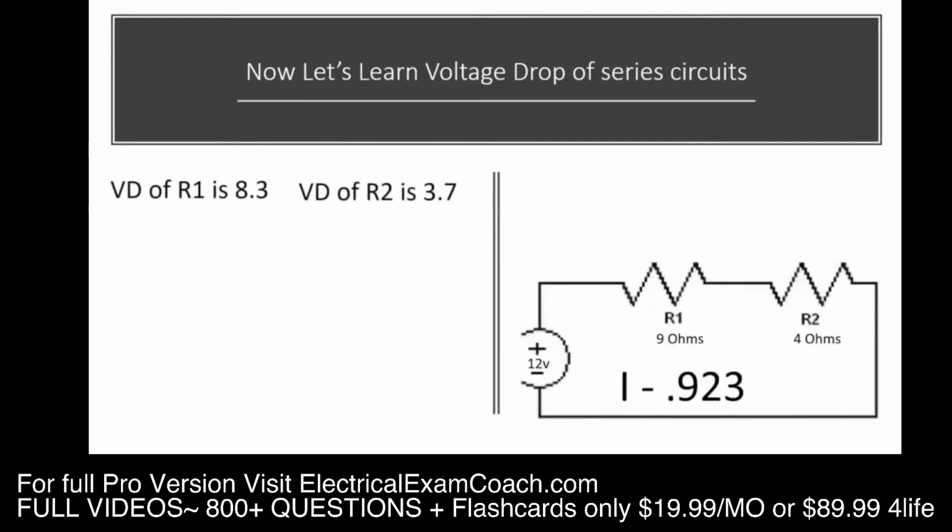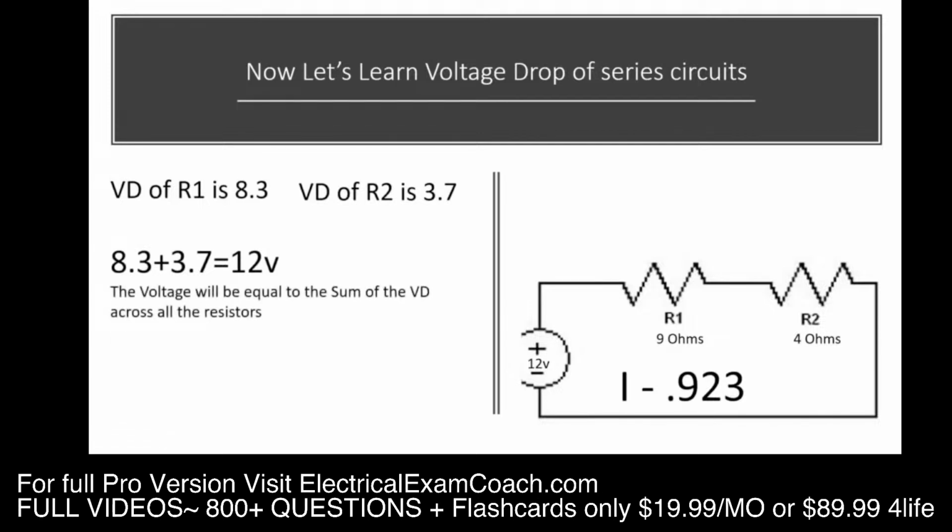Okay, a quick recap. The voltage drop of R1 is 8.3. The voltage drop of R2 is 3.7. 8.3 plus 3.7 is going to equal 12 volts. The voltage will be equal to the sum of the voltage drops across all resistors, and that's how you double check your work.